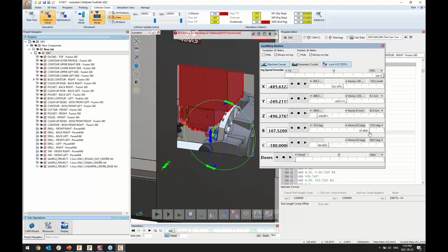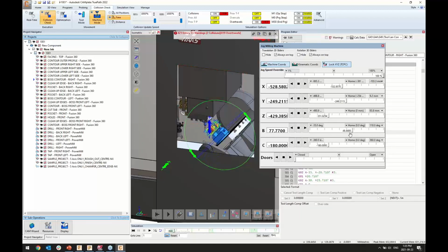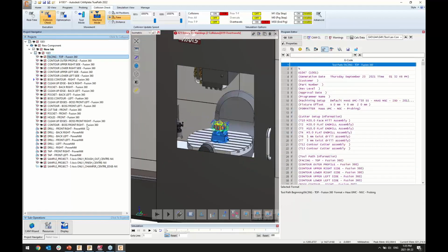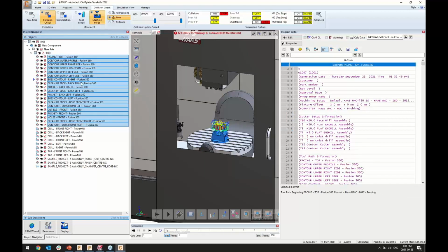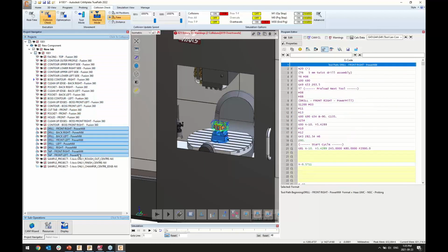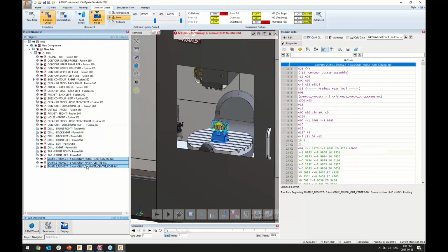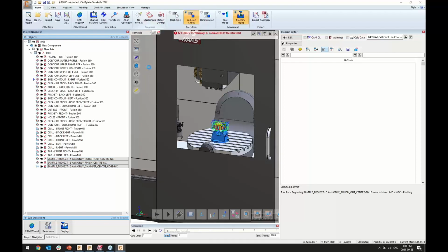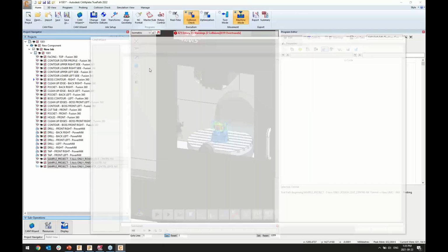So at that point, again, within the limitations of the machine, we'll want to be able to now flip that solution. Still reminding myself that I'm working in that case from 3 different CAM systems. So I'm using Fusion, I'm using PowerMill, and I'm having some Siemens settings. I have all of those points centralized in here, and all of those toolpaths are valid. We simply want to make sure that now we're able to make those toolpaths fit within the work envelope of the machine. So at that point, again, I'm not going to go back to each one of those CAM systems, correct the issue in the CAM system, regenerate everything, and re-import all of this information.